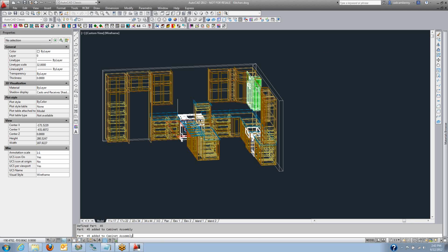So this is now taking each one of the 3D solids, and it's doing the feature recognition on them. Solid-CIM determines which side of the part should face up based on the side that has the most machining. It also rotates the part so its long direction is the grain direction in X. Now we can also specify a grain direction, using a grain arrow right on the solid.